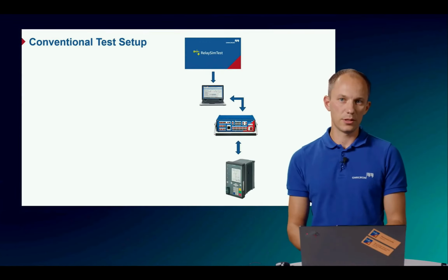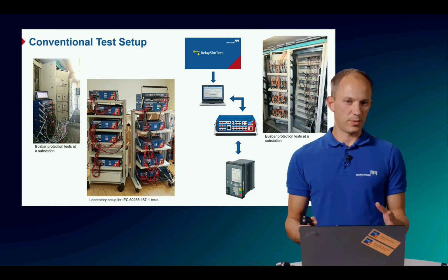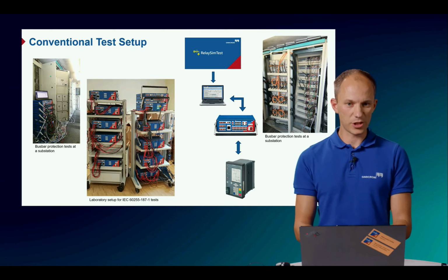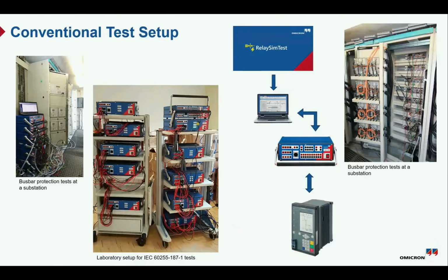The problem there is, and I have some pictures I wanted to share with you, the overall test setup. I mean, that's not a typical test setup, maybe if you test a single protection device, but you see there a lot of CMCs, amplifiers, which were needed, for example, to perform an IEC 61850 test.